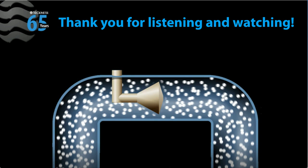Absolutely. Every customer has a piping spec, and they're trying to stay within that piping spec. And the great thing is the V-cone is built of a spool piece that matches that piping spec exactly. The only difference is we have a cone that's welded in there and a set of taps or more, depending on the customer's application. And then there's also some situations where a customer is trying to retrofit an existing line, an existing meter, and maybe that meter is not manufactured anymore, or it may have not been successful in measurement. So we're able to customize our meters and make them longer or shorter to assist the customer retrofit with very minimal installation costs and time.